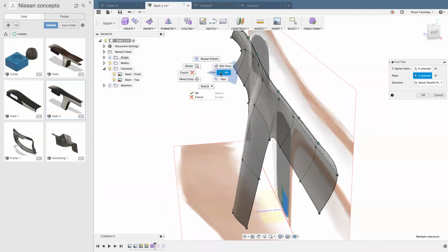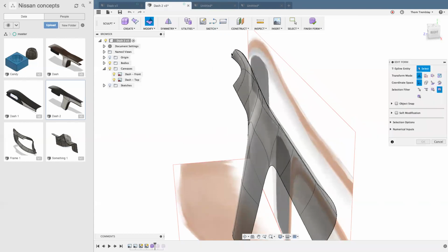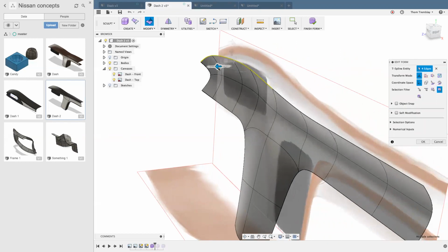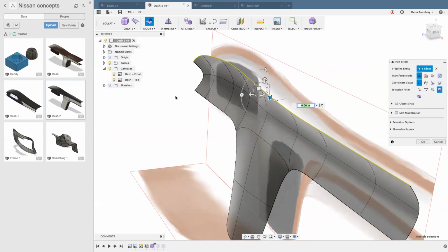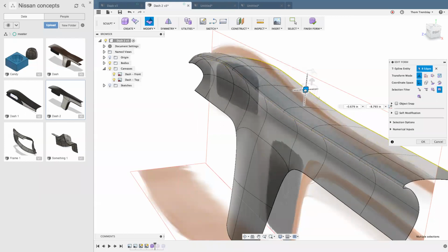Now, with that said, I'd like to bring out a portion that's going to be over the gauges. So I'll grab these edges, change my point of view just a little bit to make it easier to see, and bring these out just a touch more for a little more overhang, and maybe put a little curve to them. Now what I want to do is grab that entire top by double clicking. Yep, with a double click, holding Alt or Option, start dragging out some new faces, and by making quick click and release moves, start to drag out what will be this top portion.